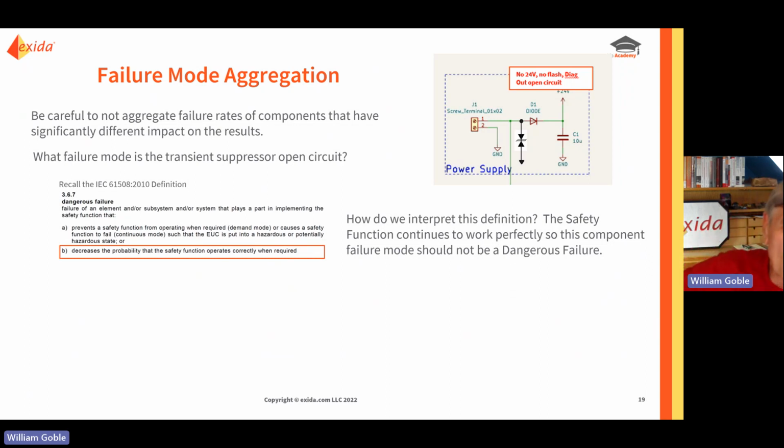So should we categorize the failure rate for this open circuit in fail danger? Well, let's ask, does the safety function still work? Yes, it does. It works perfectly. Well, then how in the world could you ever classify this as fail danger?